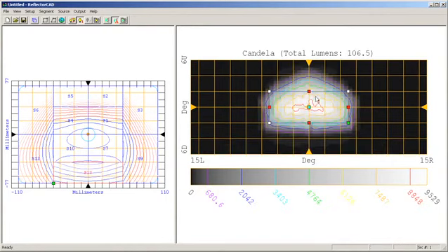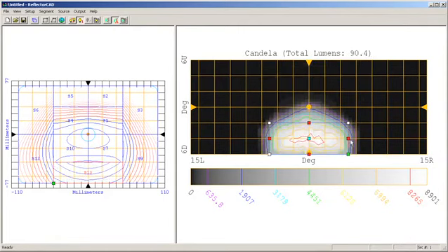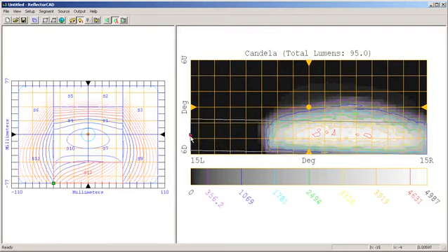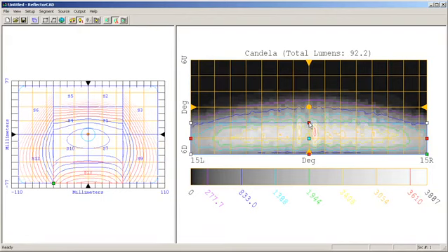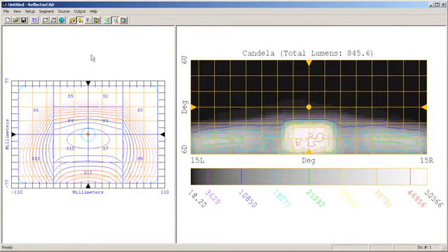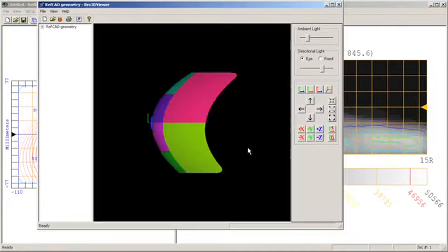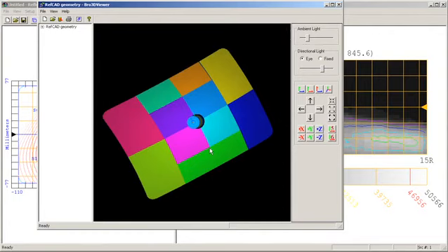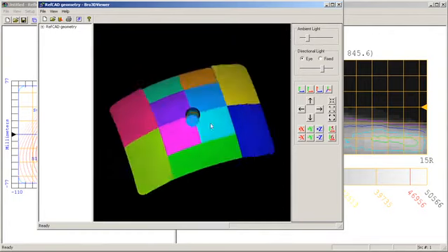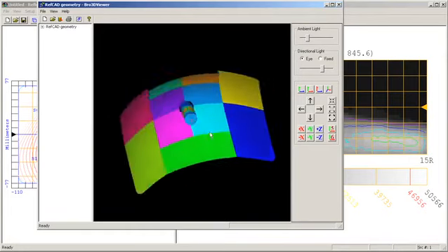Once again, the exciting new paradigm with ReflectorCAD is the ability to move the luminous intensity pattern, dragging it and dropping it to the desired distribution that I want, with ReflectorCAD automatically updating the segment itself. In this case, there is a very small, if no, inner segment filler visible, and that's probably good enough for this point in my design cycle.